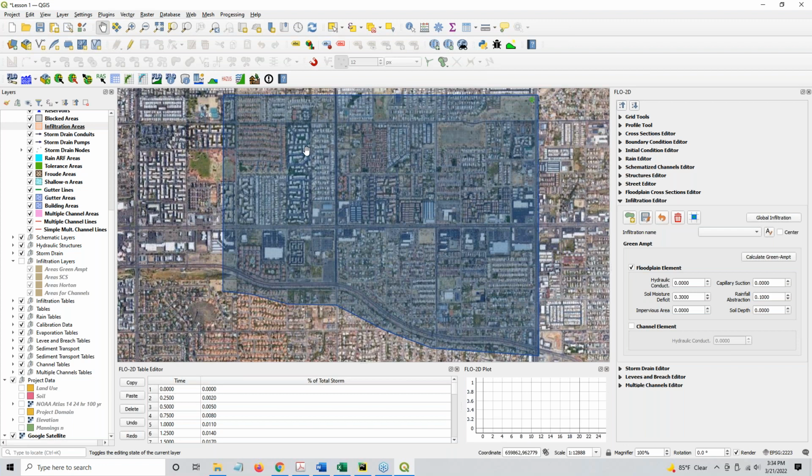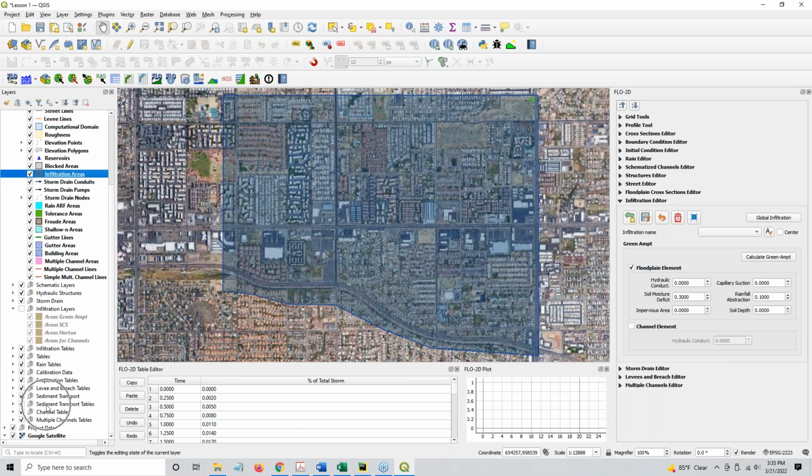So if I had my global variables set up to, say, a baseline infiltration, and then I just wanted to account for the extra imperviousness or something, then I could just put polygons in here to represent big impervious areas and give them an R temp equal to like half or 0.5 or 1 or whatever. So that about sums up infiltration, and we are basically done with that group of data. And you don't have to turn this on. You can just leave it off because you only have to do infiltration once.